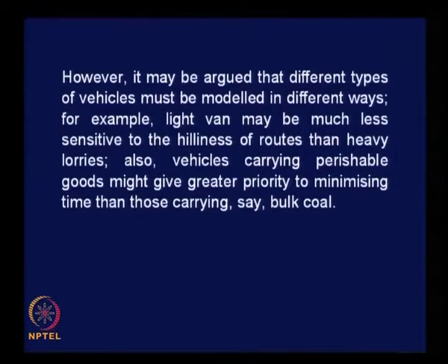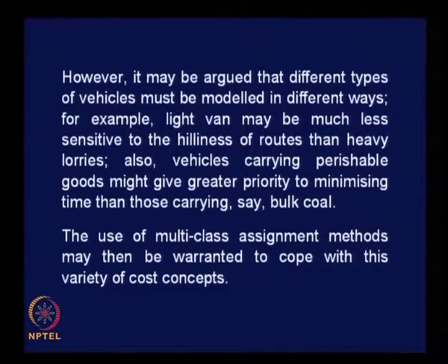Also, vehicles carrying perishable goods might give greater priority to minimizing time than those carrying, say, coal or any other bulk commodity which is not perishable. So these are other issues related to fixing or assigning routes for goods movement. So what to do? Use multi-class assignment. The use of multi-class assignment methods may then be warranted to cope with this variety of cost concepts.